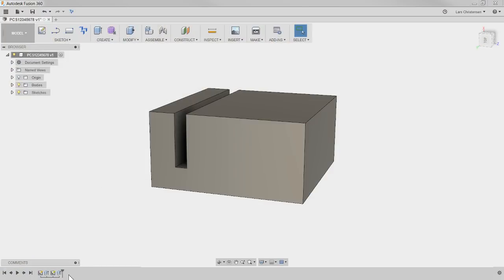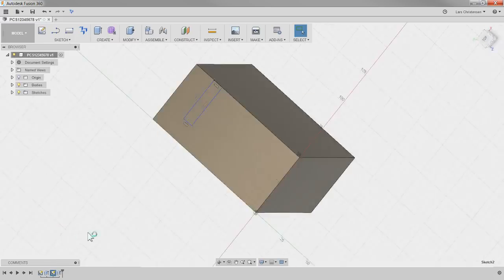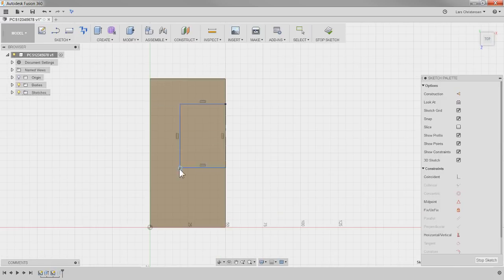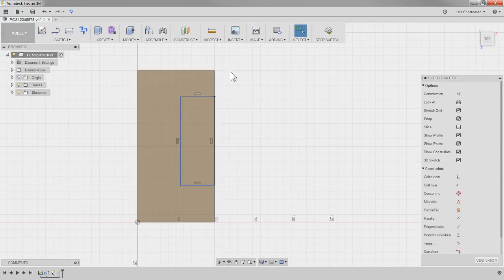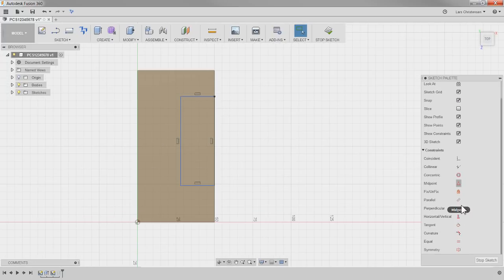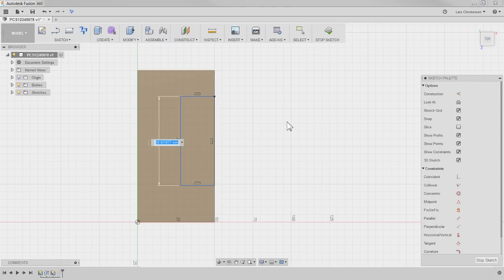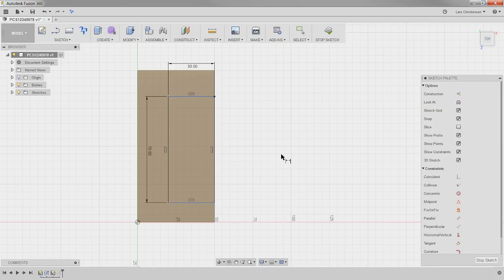That is rule number 1 in here. Always make sure that you fully define your sketches. There's different ways you can do that, but we're starting out. First of all, you can use these constraints over here, and we did a live stream on the constraints. So definitely you can look, it was one of the first ones we did. And then of course D for dimension, and we can place some dimensions in here and kind of place a length and a width. And if you ever are in doubt, you see how these two lines are still blue?